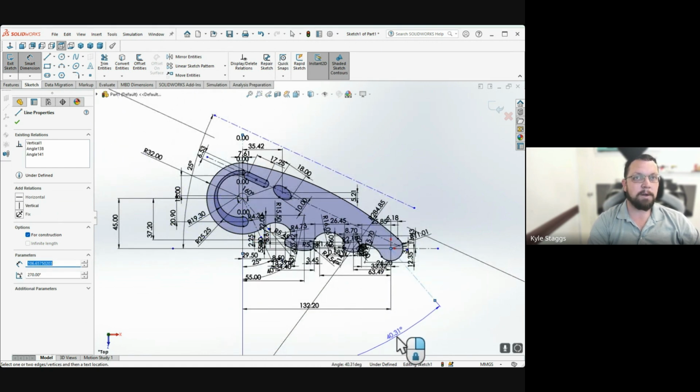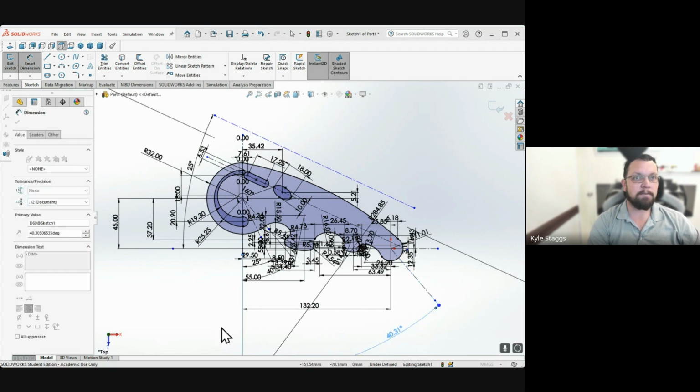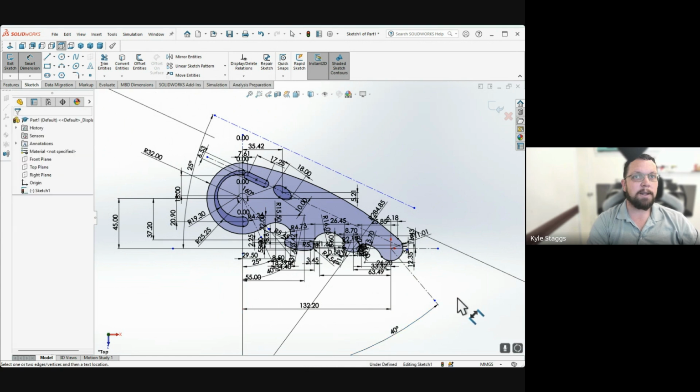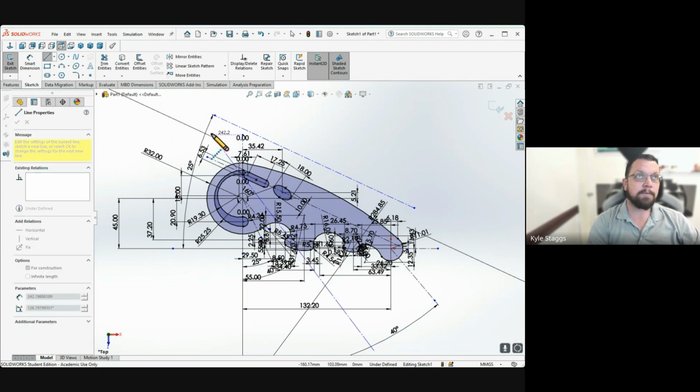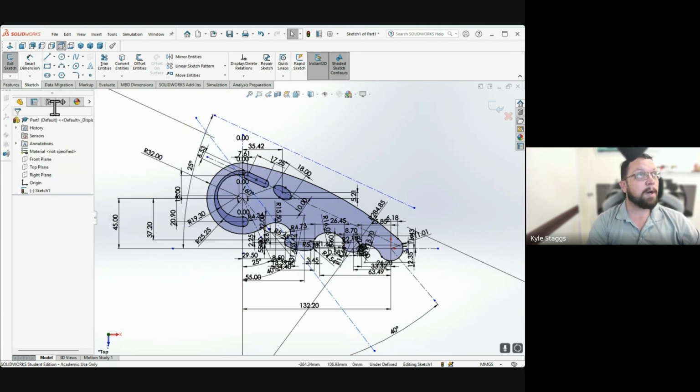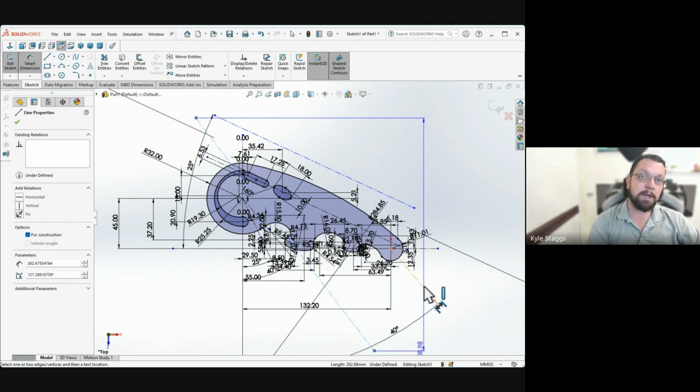Again, we need center lines in order to set angles well. So 40 degrees over here and 40 degrees over here is the same thing. So we can set up this and then say, I want to add a center line here, and I'm going to drag it all the way through the part. But I want to first start by setting the angle between them.